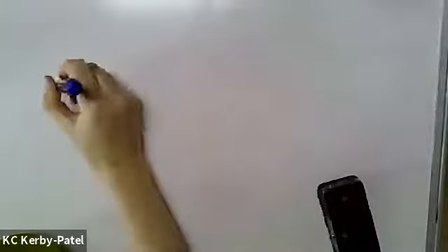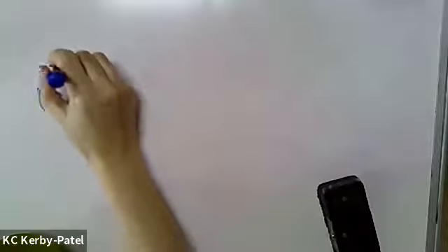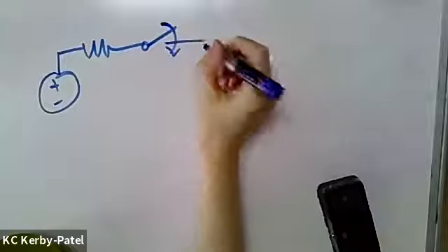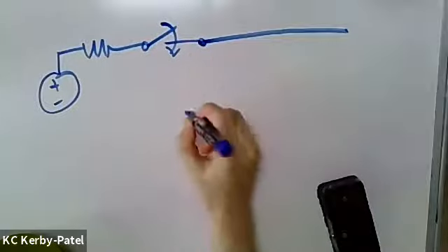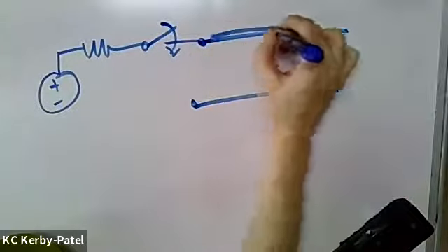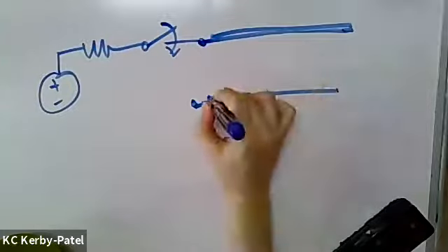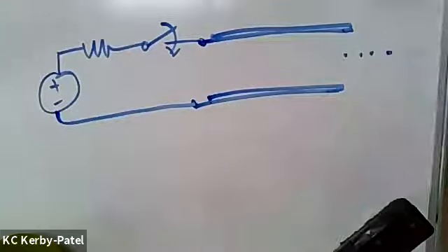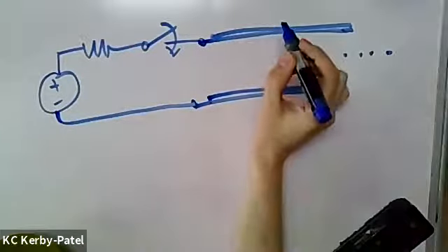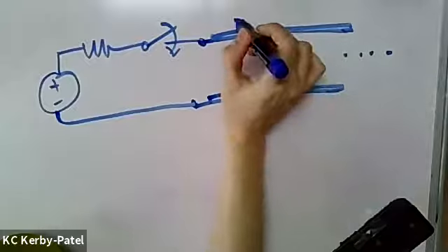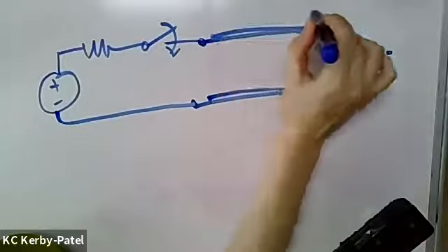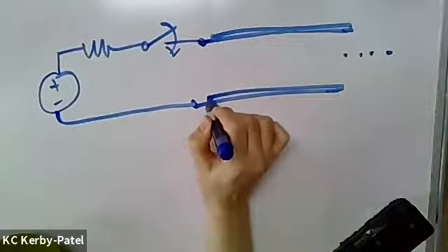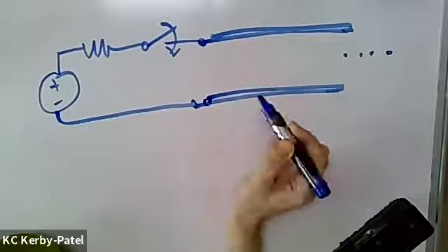So when we have this situation, here's my switch. It's being closed right now. And then we have this transmission line. Give them some thickness so you can tell they're transmission lines. The conduction current that would flow all the way down the line and over to the load and then back around is way too slow compared to the displacement current.